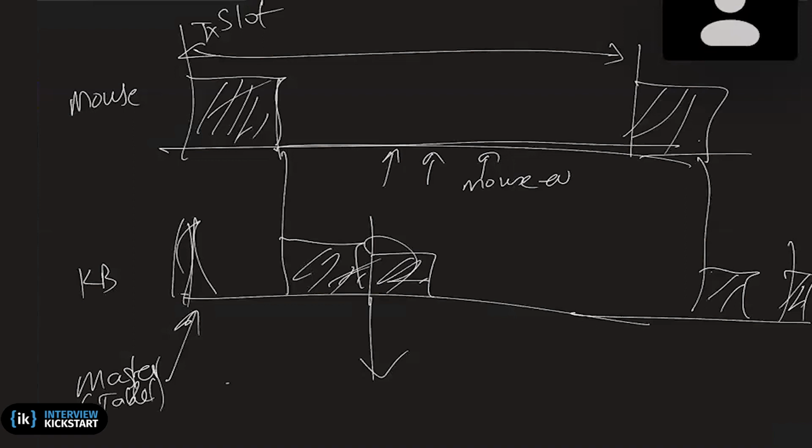So it can turn off the Bluetooth interface into low power modes. After these two slots, or it listened for these two slots, receive the packets, acknowledge them, and it turns off the radio for this duration. So basically, tickless systems allow you to program variable intervals, and this is one example where it is useful.